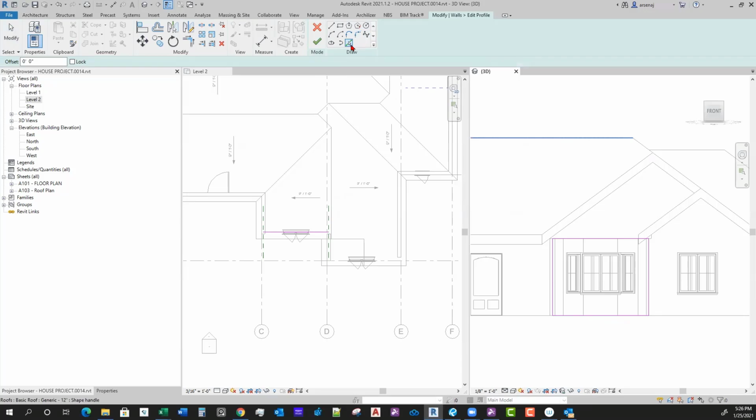So you could either just draw a line, but I always like to do Pick Lines and then trim. I'll pick lines and then pick the eaves. Then I'll escape once I've got these boundaries. Then I'll go up to Trim Corner and trim all the corners.